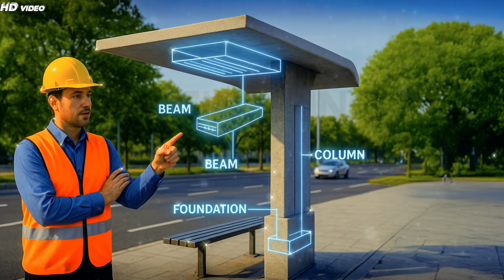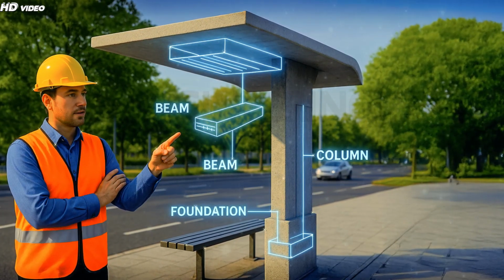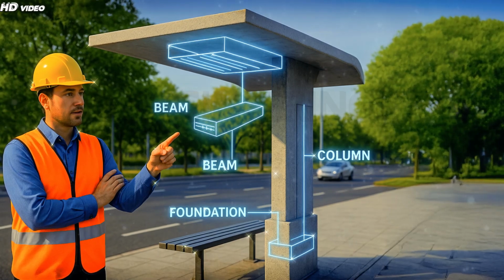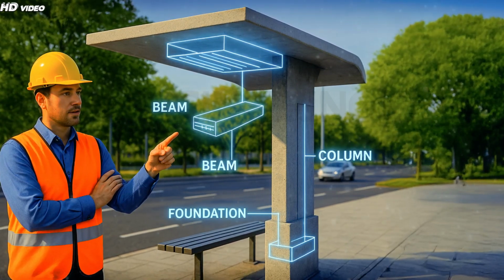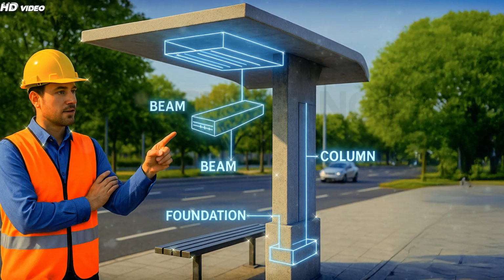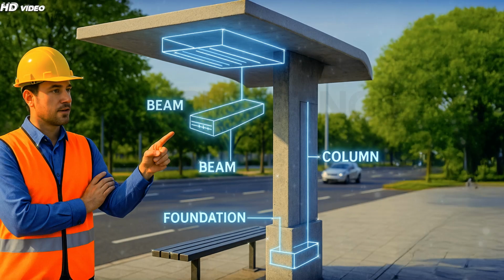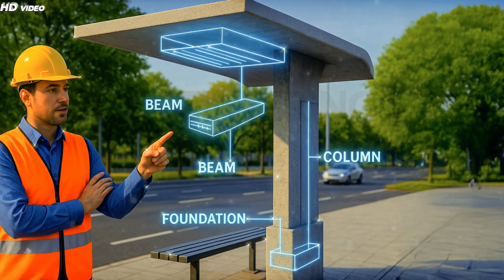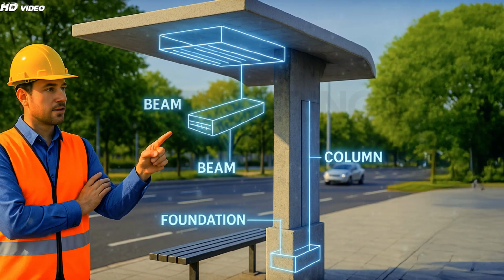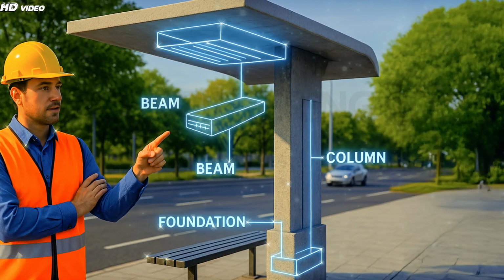Overall depth required equals 529 plus 40 equals 569. Ast equals 76,649.30 x 1,000 / (230 x 0.90 x 560) equals 660 millimeters squared. Provide four bars of 18 millimeters diameter. Check for shear.